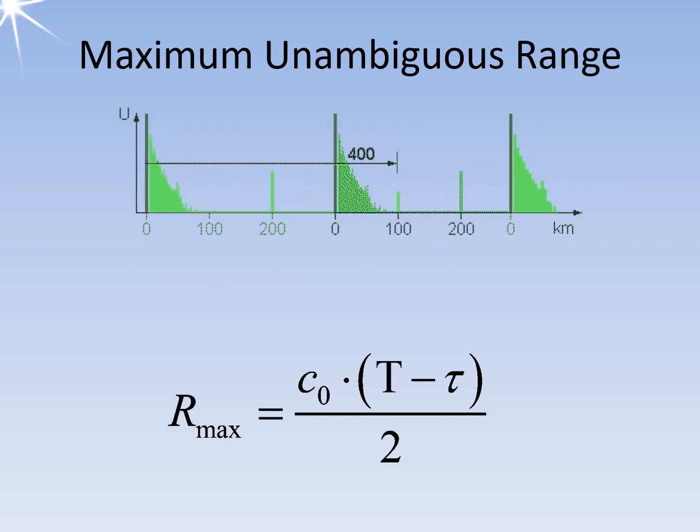Another possibility is to suppress such wrongly presented echoes with a staggered pulse repetition period. Examples are known where only two different pulse periods are used alternatively, but up to 8-fold interleaving is commonly used. In magnetron transmitters, one must ensure that such interleaving allows a uniform average power. A very long pulse period must be followed by a very short one.